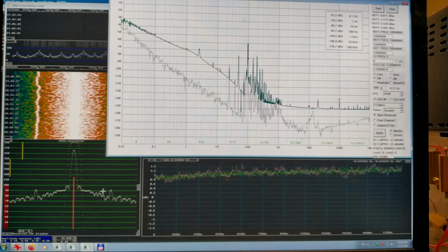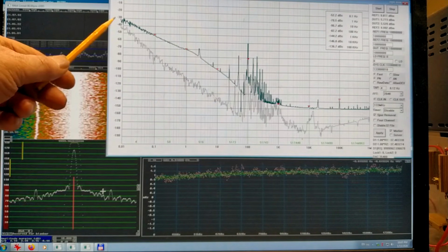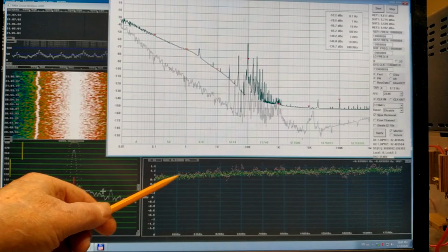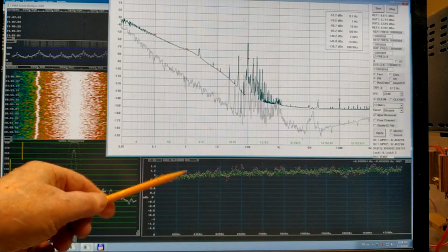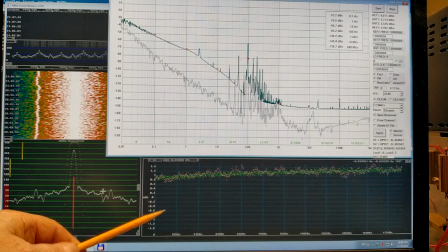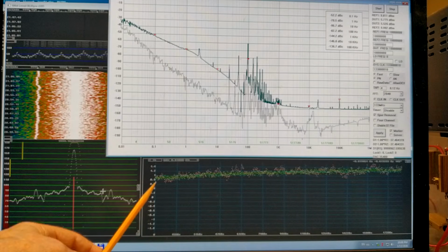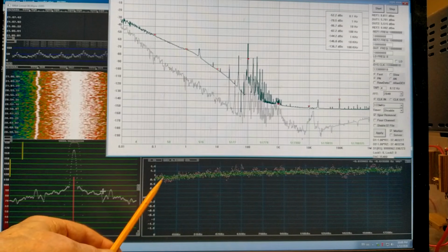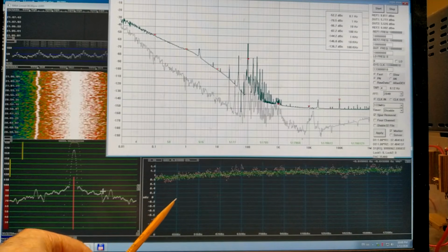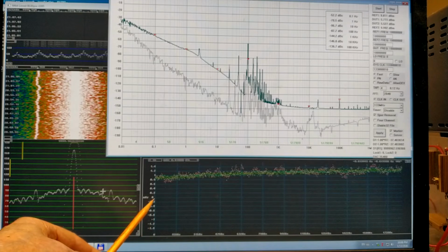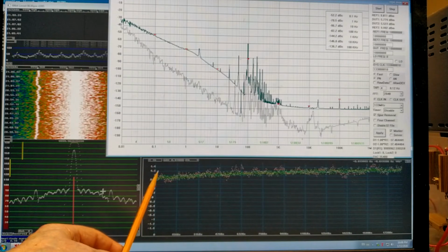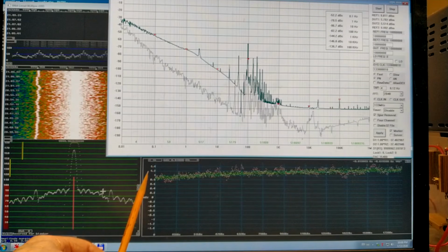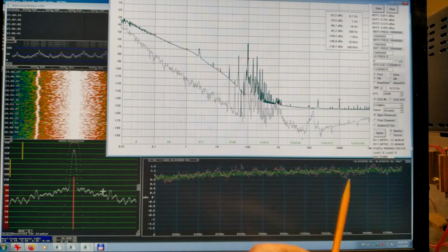And as you can see, the signal is very noisy. And if you look here, you can see the noisiness, that the dots are spread over an interval of about 0.1 millihertz. This is 15 seconds per pixel. When I switched on 6.5 hours ago, the curve started at 0. So the total frequency drift is 1.2 millihertz over 6.5 hours, and the curve is not quite flat yet.